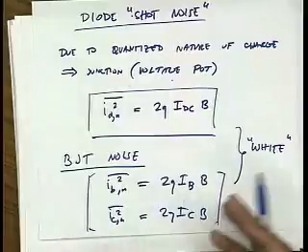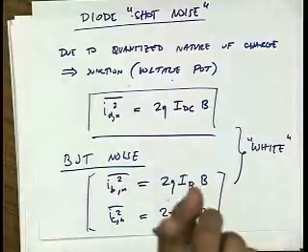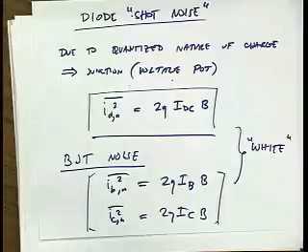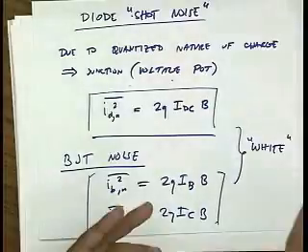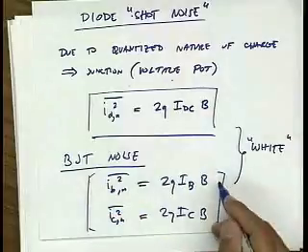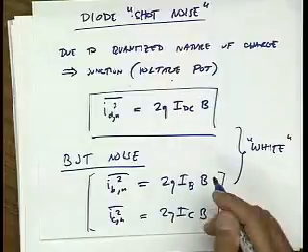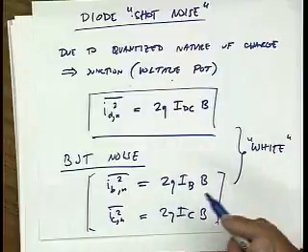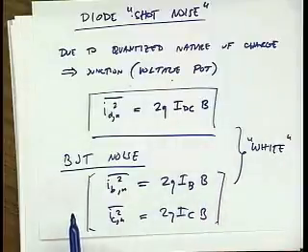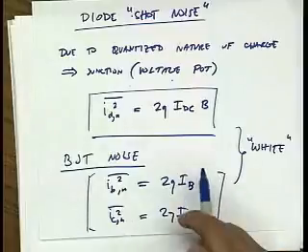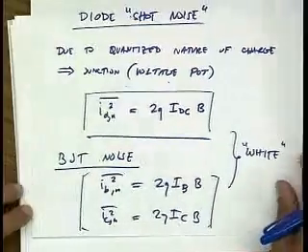Base current, though, has two components, right? It has a component that goes to the base collector junction. That should hopefully be a small one, right? Most of it is going through the emitter. And that's actually a different junction, so it's a completely different event. In fact, the collector current is mostly due to electrons injected from the emitter, not from the base, right? So these are not correlated. They are indeed independent.